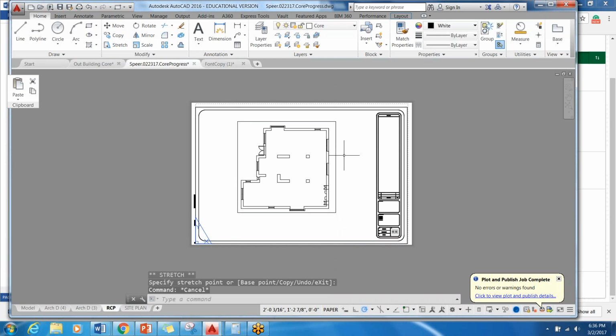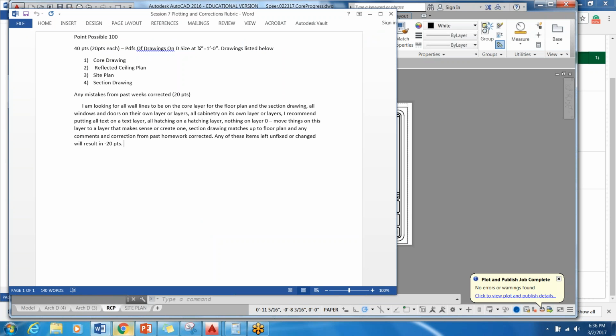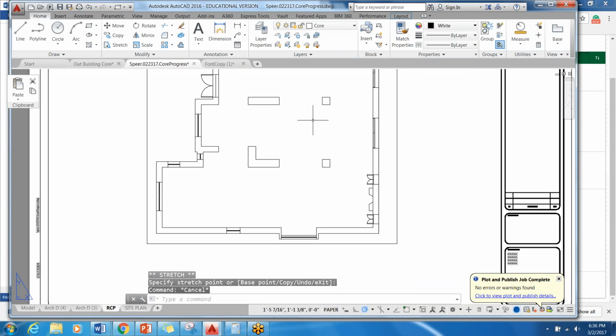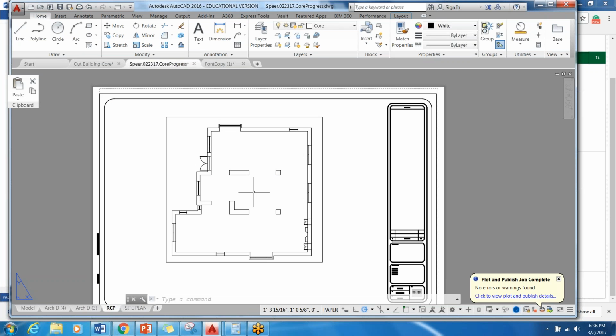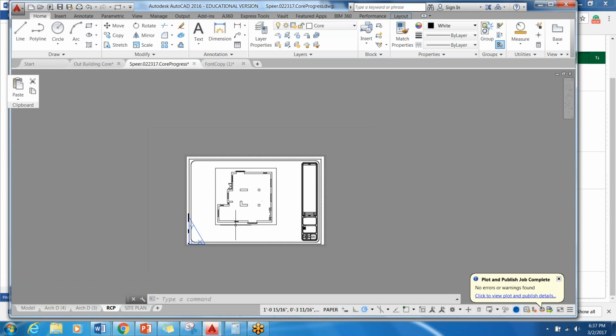So this is where the two things are going to come in. This is really step 1, but I needed to talk about text because we covered it earlier. So then she would want to go into her file that I had open earlier and find the text height for all those little words, which you guys already have set up because I'm not making you change those things from last week. They're already set up to be the right model space heights to reflect fine on a 1/4 inch scale. I did those heights from model space and gave you the right values so it'll read fine.